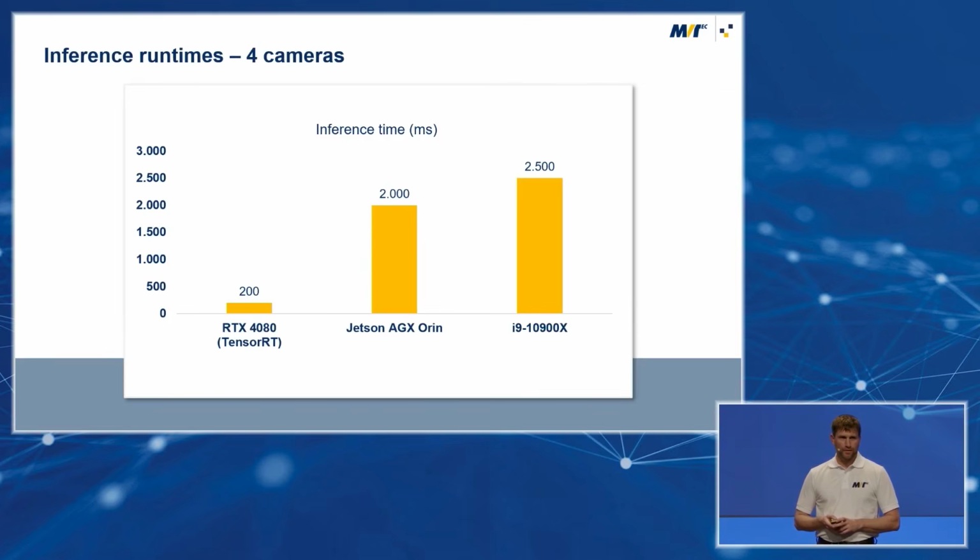That's it. We had a benchmark, 4 cameras, 5 parts in it, and we had 200 milliseconds on a consumer GPU, a potent one, here the RTX 4080. Do you know what that means? 200 milliseconds for getting 5 poses. That's not a bottleneck anymore. The robot has to pick them, has to do some work. So it's a very, very short time for this situation.